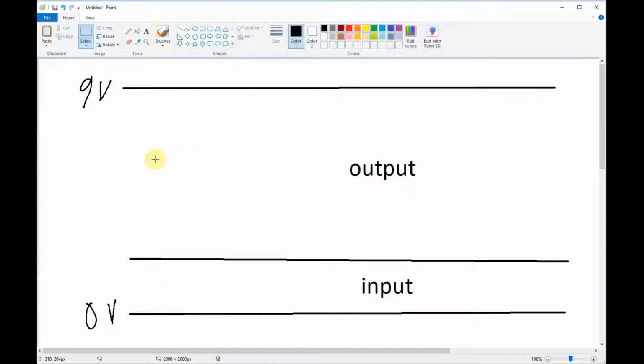I mean, I don't know why people don't talk about that. They just get straight into the biasing and all the algebra and so forth, but this is a fact of the matter. So if this is reserved for this, and this is reserved for this, then you're going to set usually your input halfway in between there and halfway in between there. So let me draw that and we'll pause.